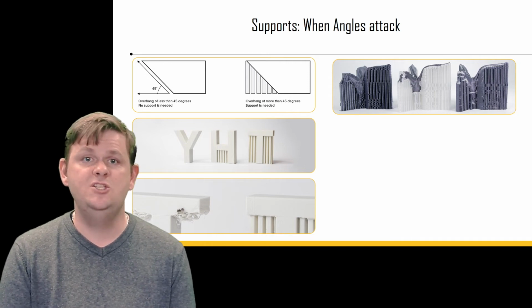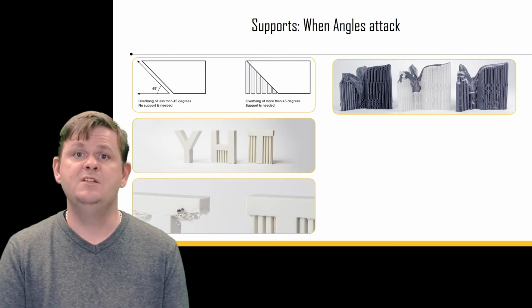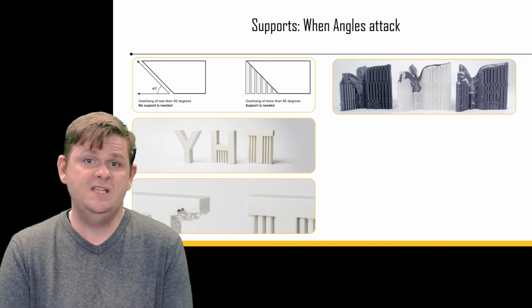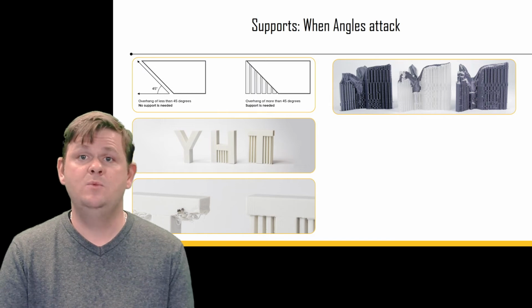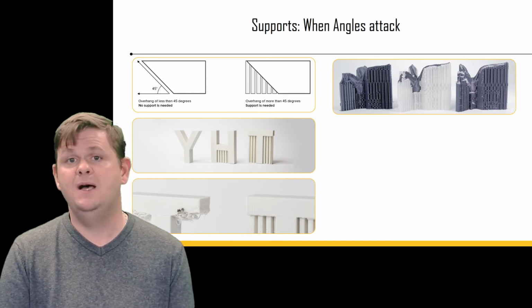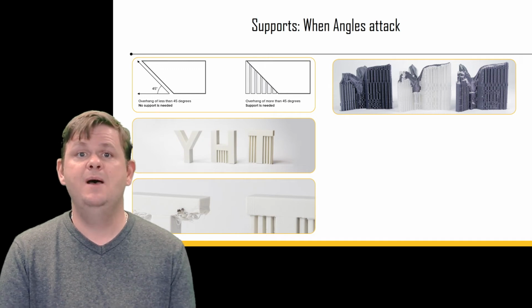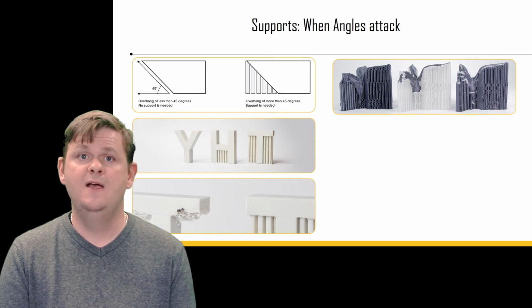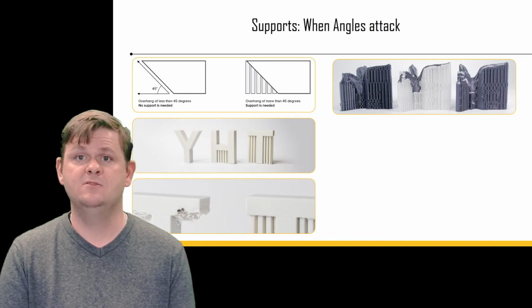And finally, the T shape is the most wasteful because it requires almost as much support material as the part itself. That said, if we think outside the box, we can orientate all 3 letters to print without support by simply lying them on their backs. Alternatively, parts which may require a lot of support can be split into separate components. Think outside the box when it comes to designing angles into your parts.